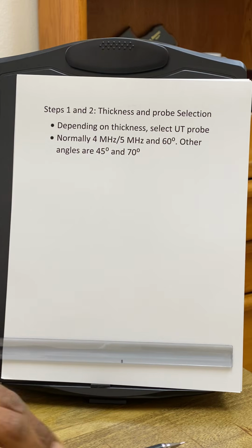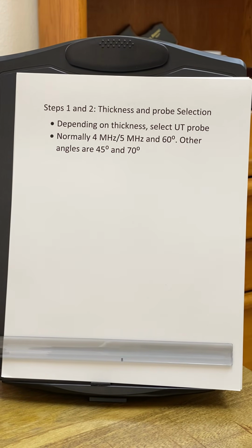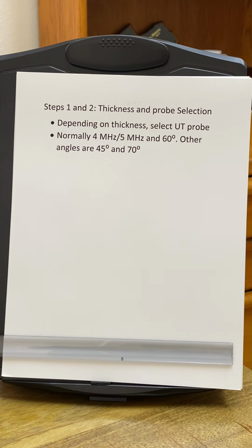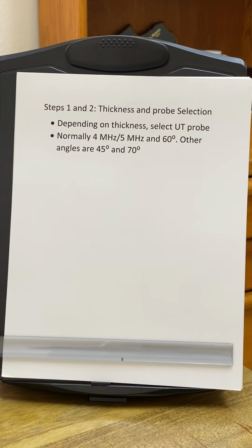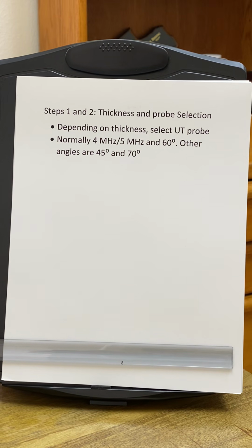So now steps 1 and 2, thickness and probe selection. Depending on the thickness, we will select the probe. Normally probes are 4 megahertz or 5 megahertz, and the common angles used for angle beam testing are 45, 60, and 70 degrees.